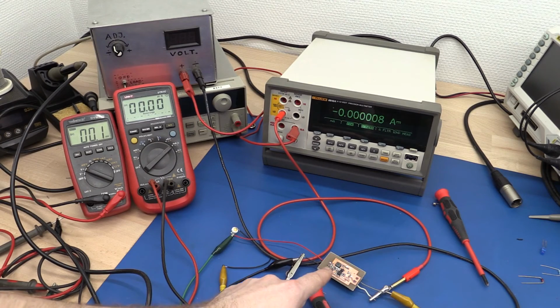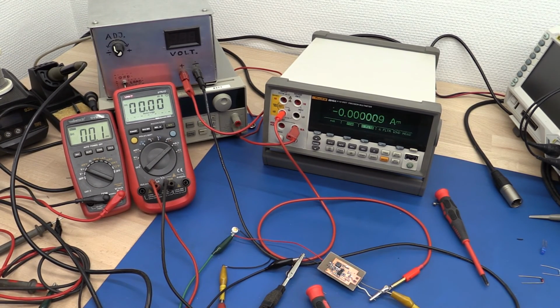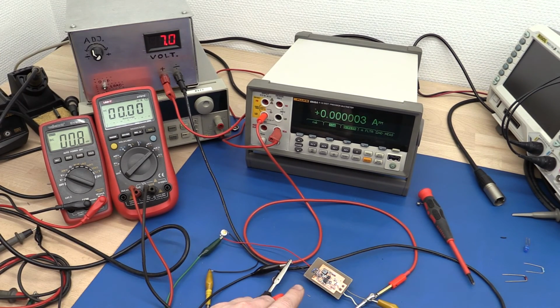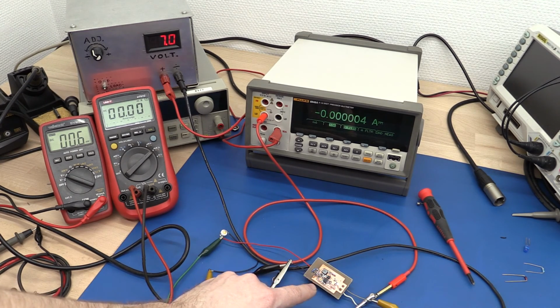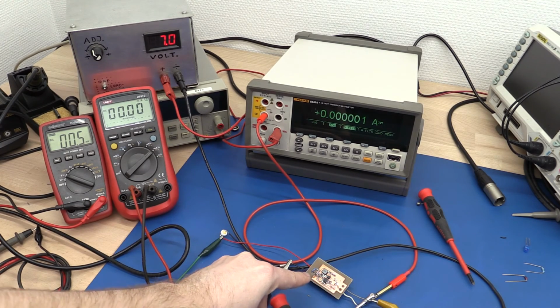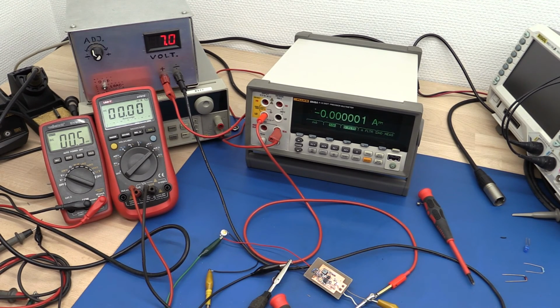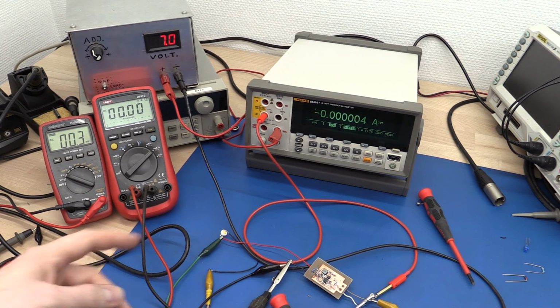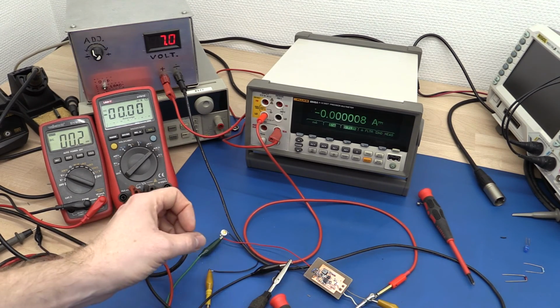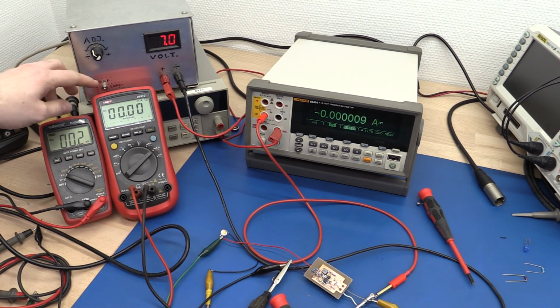I can try to hack in a 1 ohm resistor and momentarily run it at 230 milliamps. I didn't have any surface mount 1 ohm resistors, so I just used a leaded. Actually I chose 1.2 ohms because I already have 5 ohms SMD on there. So I just put it across it so I can pull it off again. We have to be fairly quick because the LED will warm up very fast at 200 milliamps.